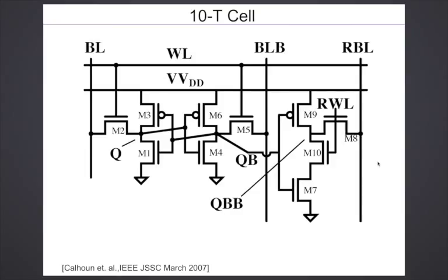So with series stacking, the question is basically, why not use one transistor with double the length? Now you have to be a little careful because of the impact of length on the threshold voltage, so you have to take all that into account. You can have a short channel effect, which helps by increasing the threshold. But if you have reverse short channel effect, it can go the other way. So you have to take all those things into account when you do this.